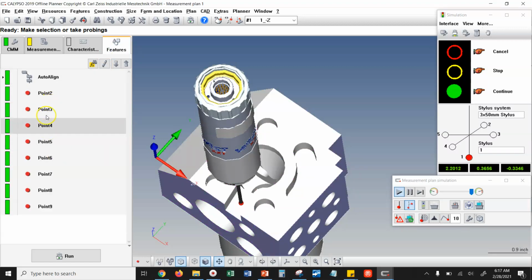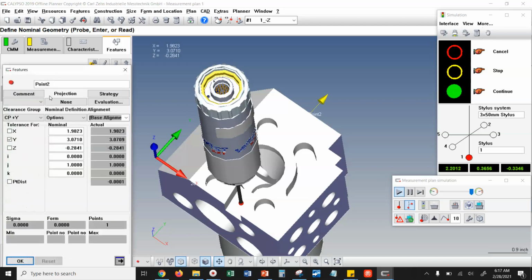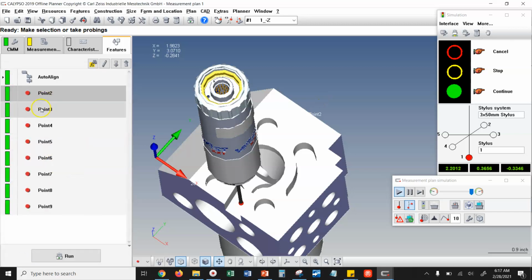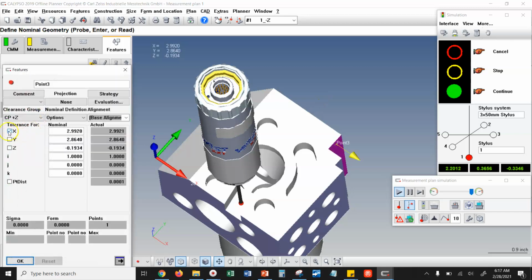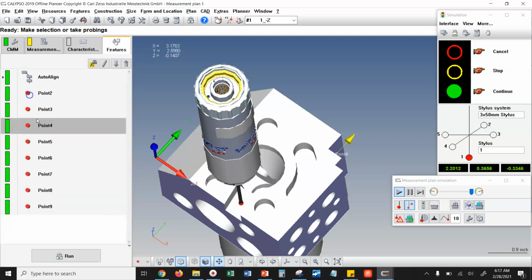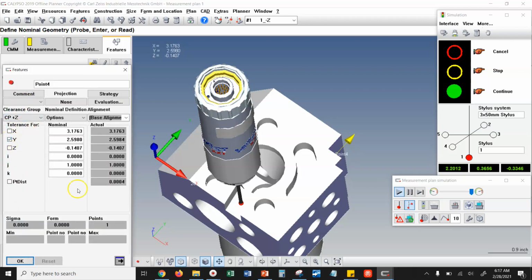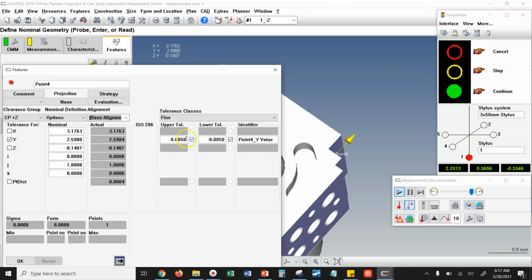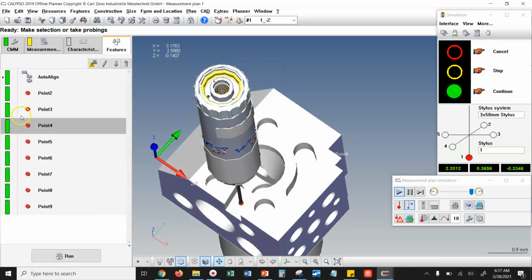All right, so all of these should be able to have direct characteristics. I did create some of them as I was going along. If I hadn't created them as I was going along, I could simply do so right now. Now you see this is already in here, so I'll just say OK. And I'm systematically working down the list. This one is already in here, so I'll say OK. 0.4, that's already in there. If I want to see more details, I can always hit this little arrow out, and that shows me my tolerances and the default name of the characteristic.